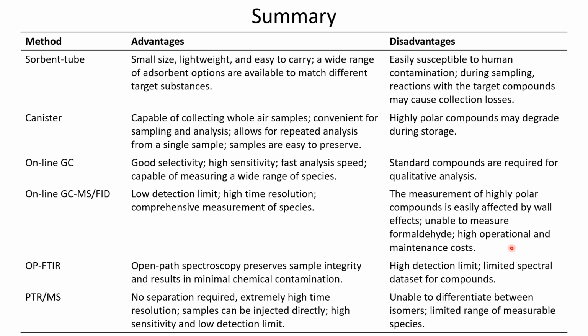high operation and maintenance cost. And then open path FTIR, it is open path spectroscopy that preserves the sample integrity and results in minimal chemical contamination. But the detection limit is higher, and we need a data set for the components.